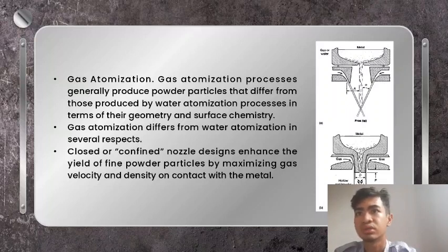During the gas atomization process, the liquid metal is disintegrated by a high-velocity gas such as air, nitrogen, argon, or helium that is driven through a specially shaped nozzle. Atomization occurs by kinetic energy transfer from the atomizing medium to the metal. To visualize this process, the breakup of the metal stream into fine droplets can be compared to the way that gasoline is atomized as it passes through the Venturi nozzle in an automobile's carburetor.